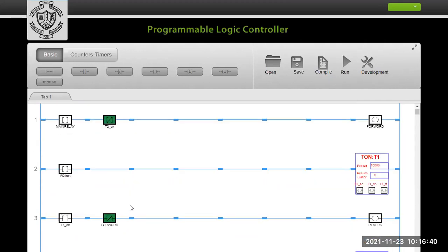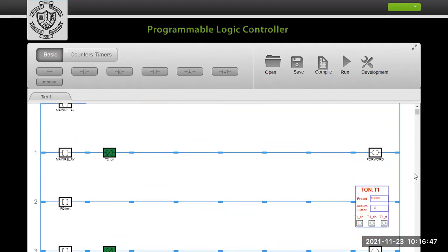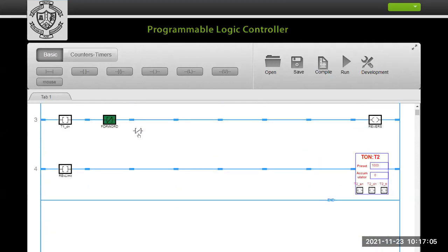Another limit switch is required. When the limit switch is reached, your crane also stops. Otherwise, after getting to the destination, it will always try to keep running, so it will damage the platform. So you have to take some protection. When the limit switch is there, you have to stop.